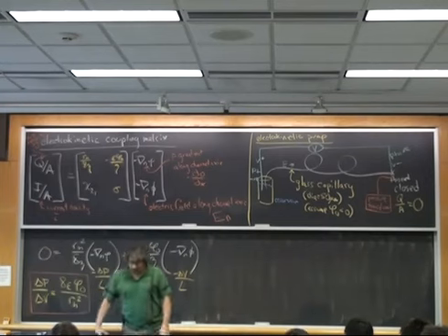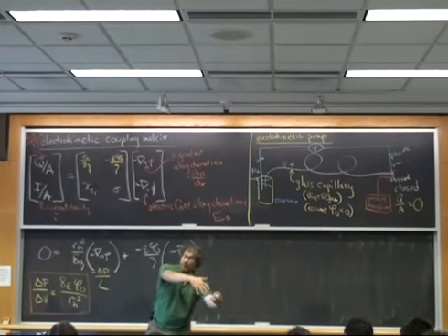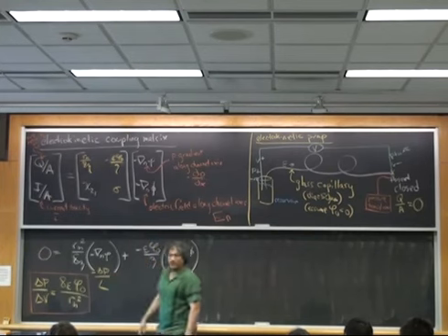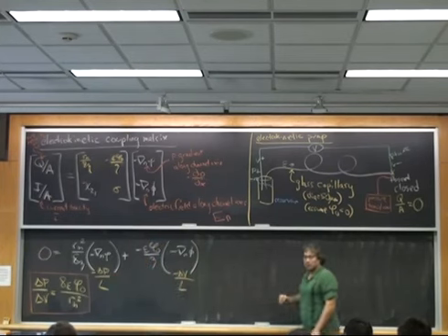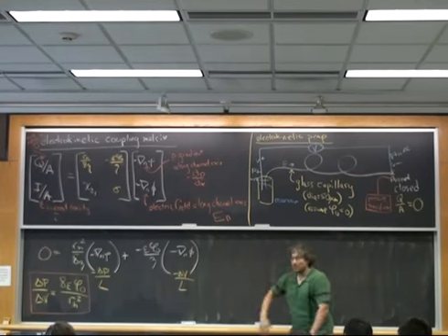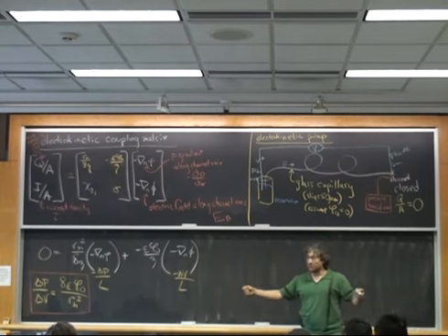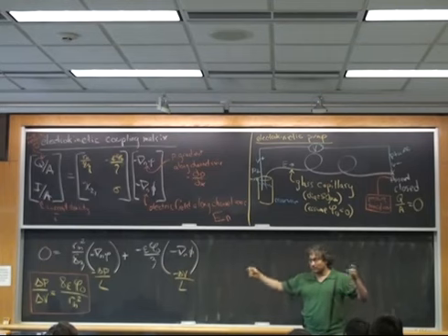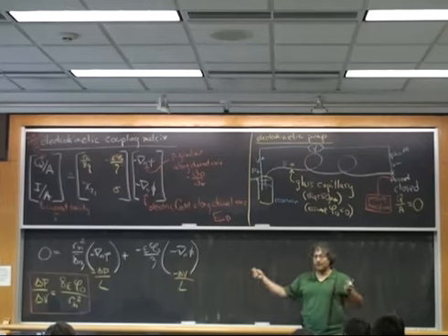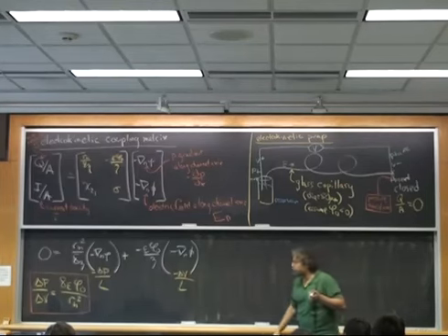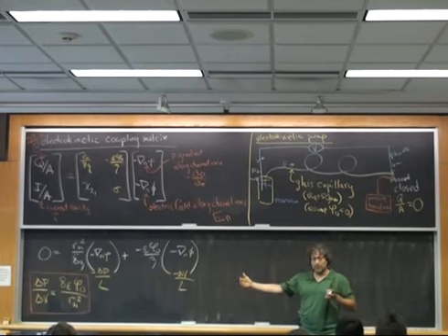And so this means that if I take a big, meter diameter glass tube, and I say, yeah, electrokinetic pumps work, I'm going to connect it to a high voltage power supply, awesome, right? My flow rate's proportional to the area, so I get tons of electroosmotic flow rate, super awesome. And then what pressure will I generate? Nothing, basically.